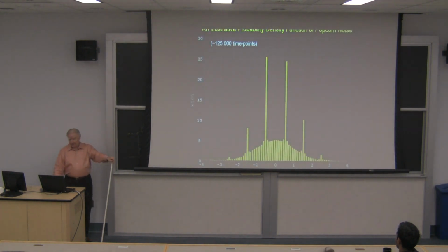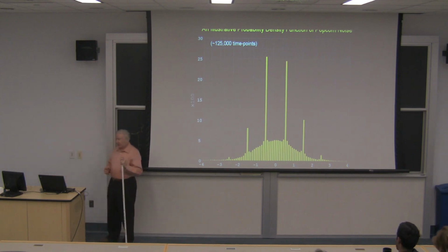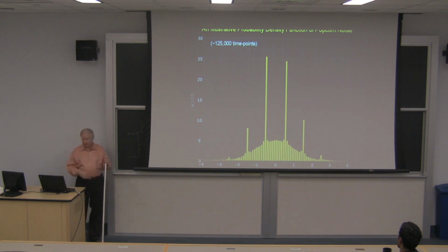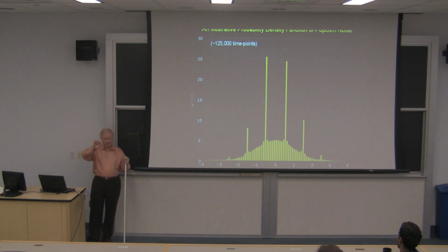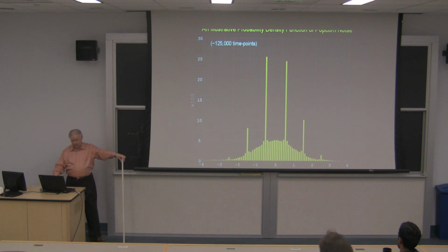So, okay. Now this is another kind of noise. This is called popcorn noise. And it used to be a big problem at one time in NPN transistors. And it's, again, one of these trapping phenomena. But what we see is a base that is mostly Gaussian. That's the white noise component. And then these energy levels that are discrete and ratioed in a very particular way. And those are due to the trapping phenomena. And it would lead to, I don't think I have a picture of the waveform, but a waveform where you have noise and it will step to another level and step down to another level. And there are only about a couple of levels where it jumps between, but it'll occasionally jump to a higher energy state. And that's pretty much gone, I think. But if you hear about popcorn noise, that's sort of the nature of it.